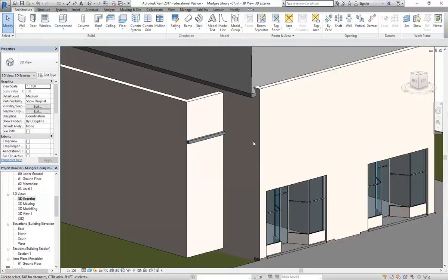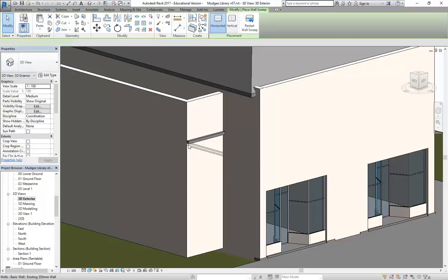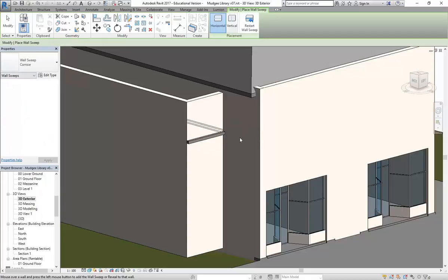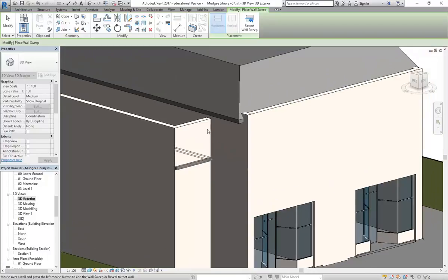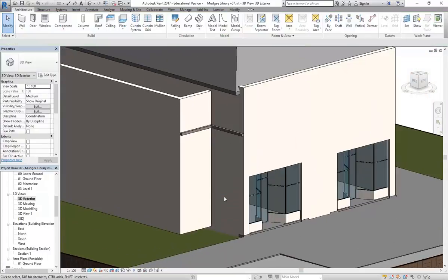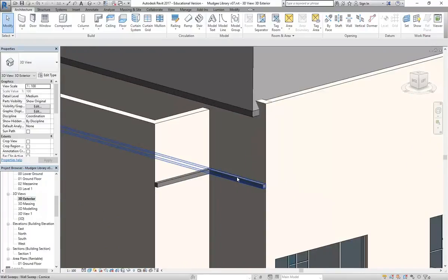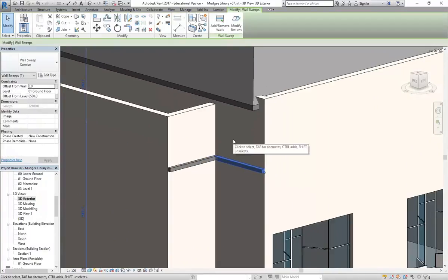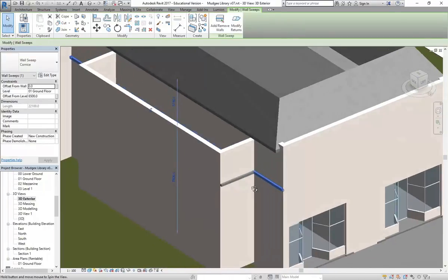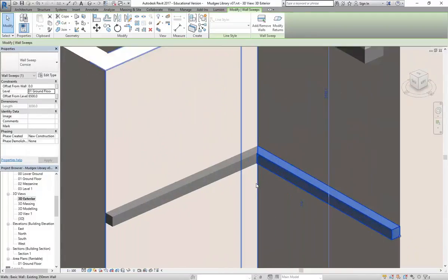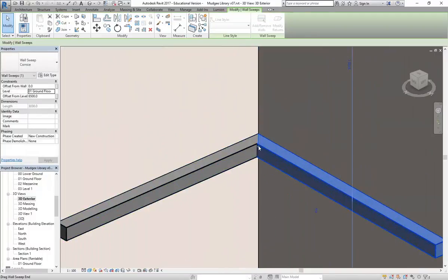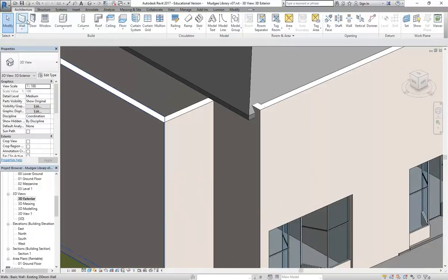So there, it's put it in, and I'll go and do another one now to try and extend that by choosing this other wall. And it's a bit like a few of the other tools in Revit. I don't think that the developers really know how designers work, and they've never really made this tool all that functional. So it's got these two cornices there, but they're separate. I can drag the ends, but they're still not going to join very well unless I play around. So you can see there, that's joining, but they're two separate cornices. So I'll delete those, and I'll do it another way.